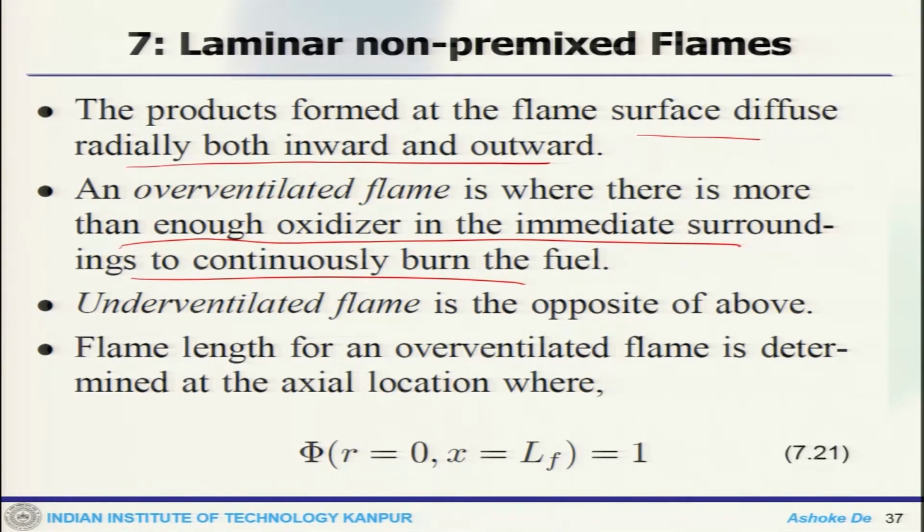Now, the flame length for an over ventilated flame can be determined at a location where phi is 0 and x is LF and the phi is stoichiometric.